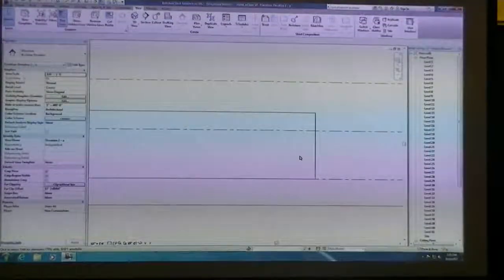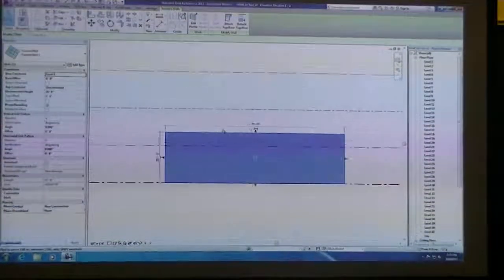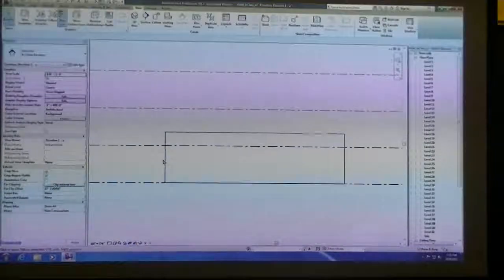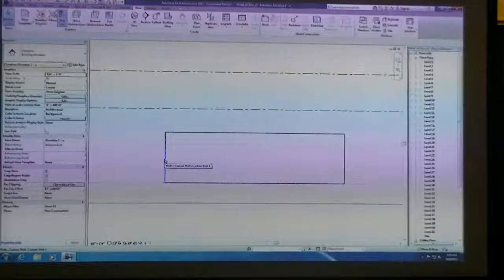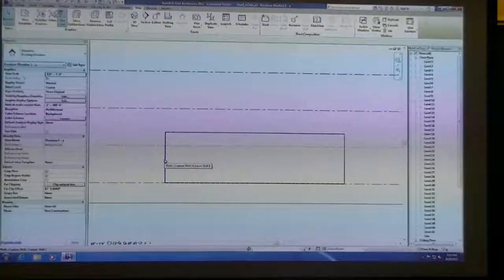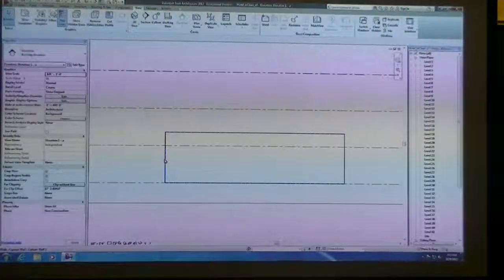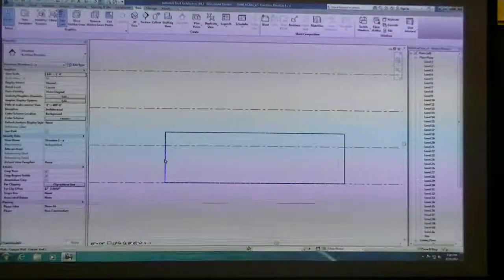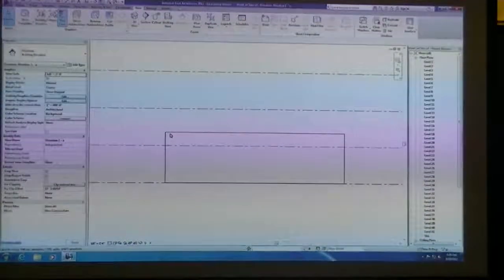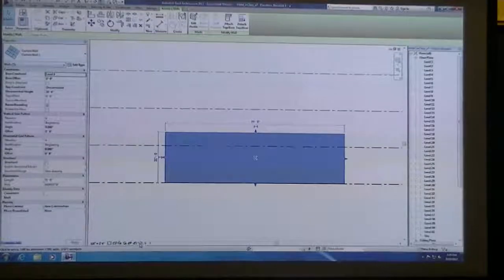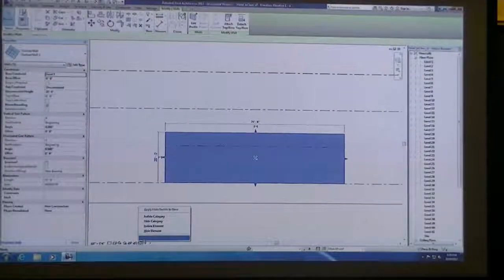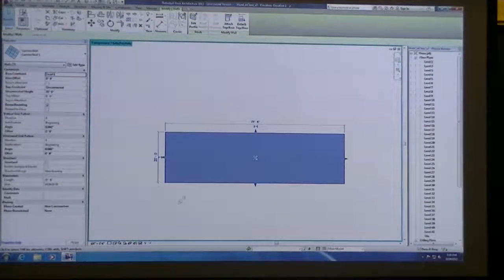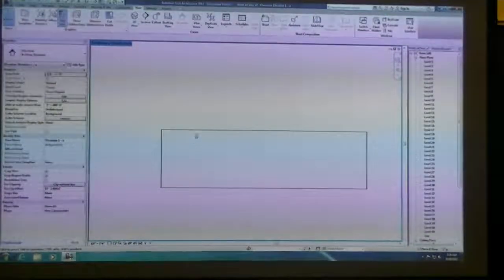And we're going to have to zoom in where it's located. And if I were you, because there's so many things that will occur in your model from time to time, especially if you're doing a very complex model and you've got tons of walls and rooms that are showing up in this elevation, click on your glass and your temporary view settings, choose isolate element. That will only show that one element that you selected.